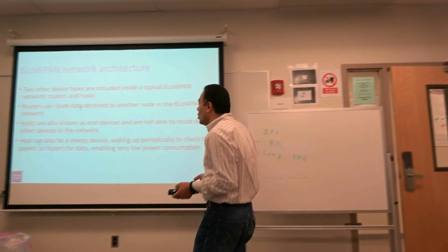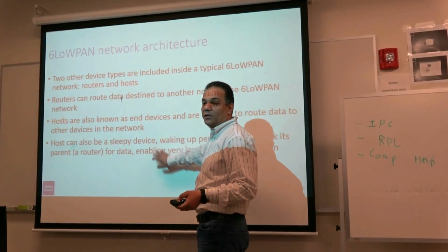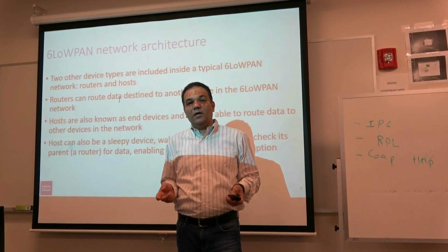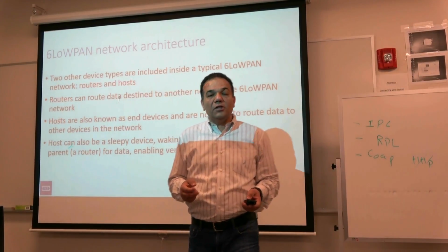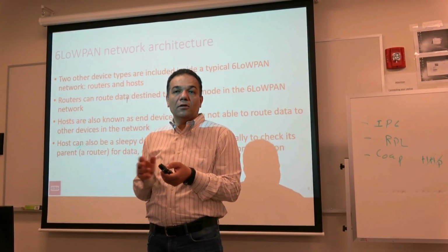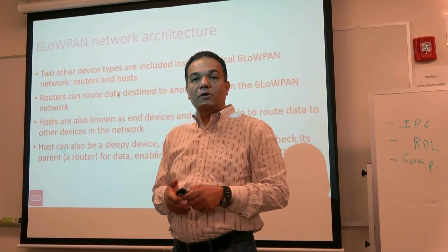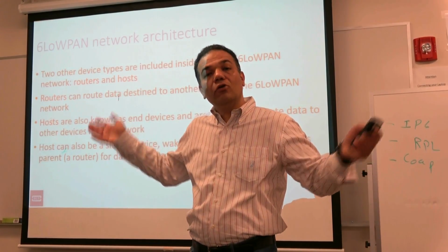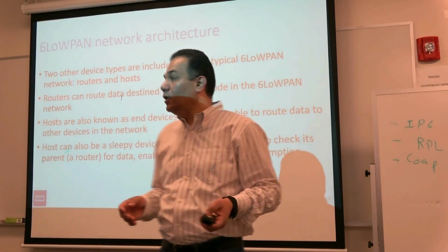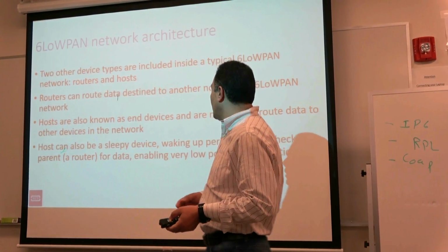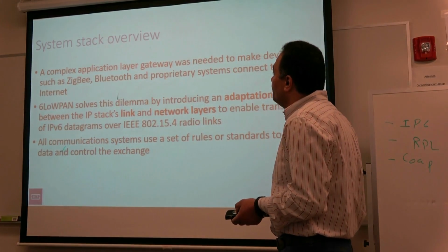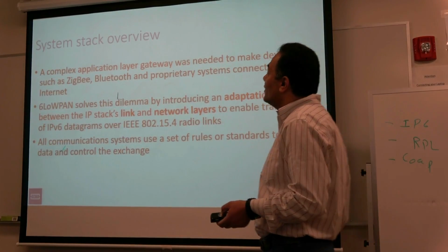So a host can also be a sleeping device. And that's the whole idea. We need to conserve the power, the energy in the device. So these devices are programmed to sleep for a certain time and wake up at certain times to communicate, to save power. Our goal is to keep their energy, their battery, for a long time, okay, for an extended period of time as much as we can. So we have the sleep and awake issue as we have in most of the wireless devices. All right. So let's take a look at the stack overview.